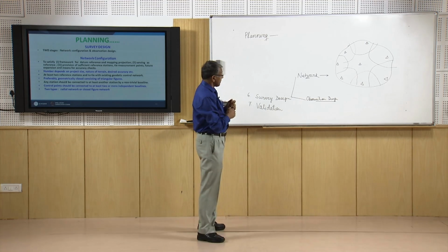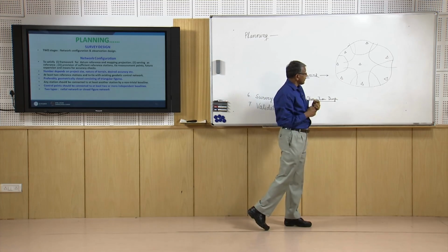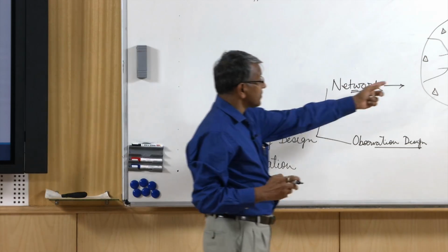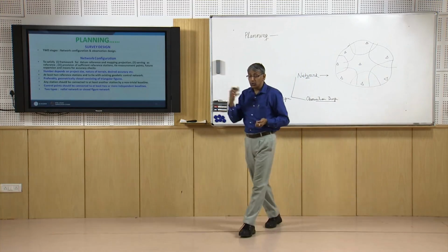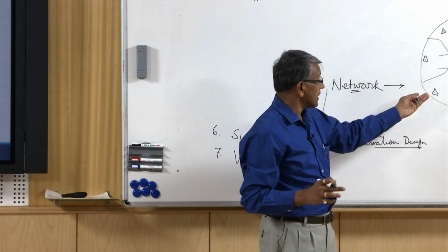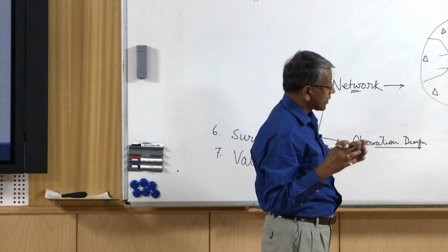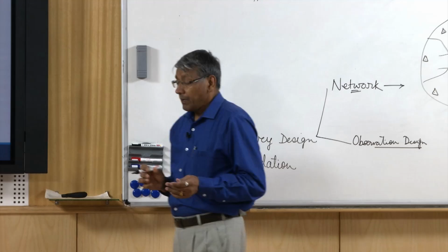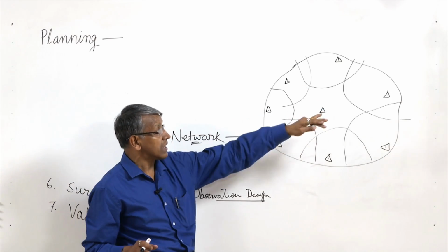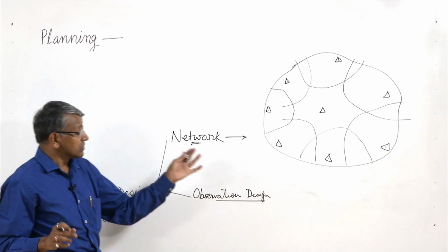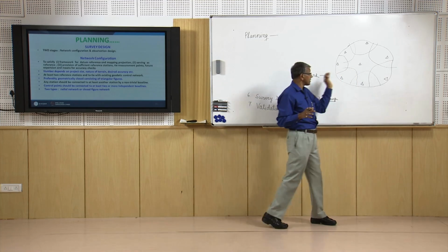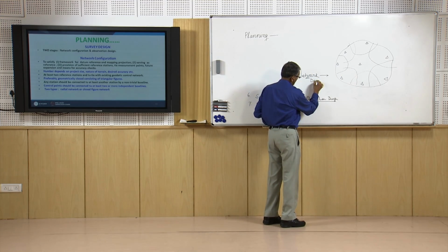Another important point is, not only the number, but these stations should be tied to the national surveying network, so that we can have the local network system, and also it should be designed in such a way that in future we may extend our network. So these are the primary points which we should keep in mind during the network design.